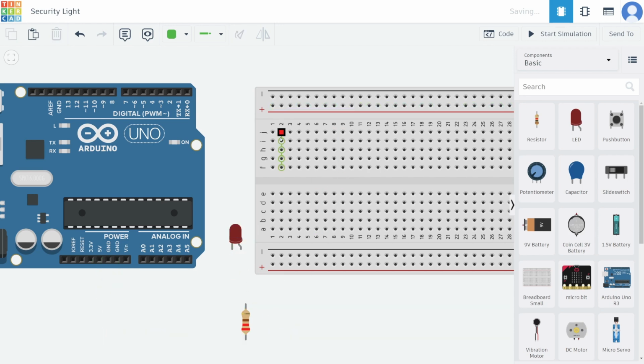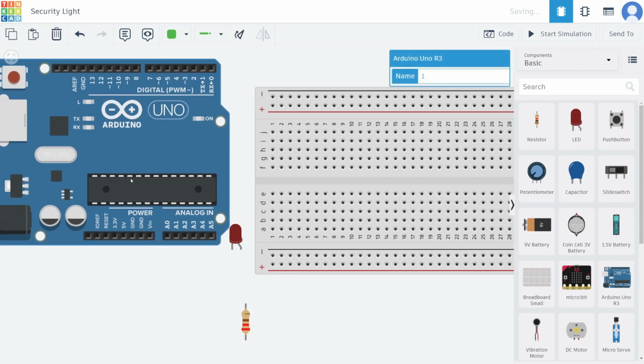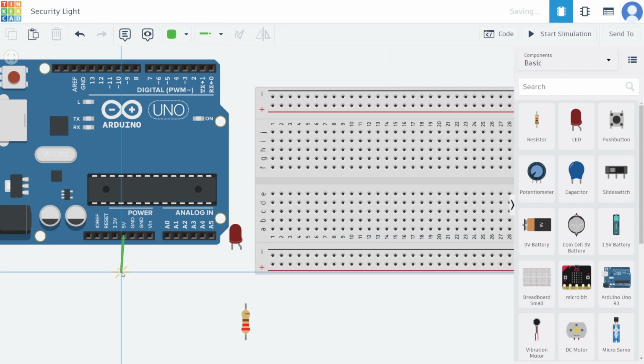Okay, so the basic idea of the breadboard is that you can put in, and you might like to go and get yourself a physical breadboard to have a look for this to make more sense, but all of these pins can actually be pushed down into these holes on the breadboard, and likewise the wires have pins on the end of them that can be pushed down into here. And so what you can do is you can, for example, take 5 volts here and connect it up to one of the pins. So imagine that you've pushed the wire down into the 5 volts and into this hole.